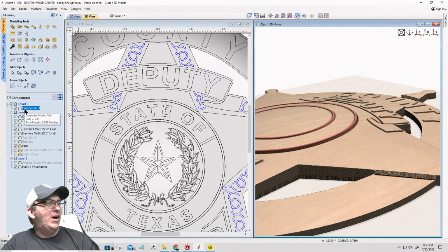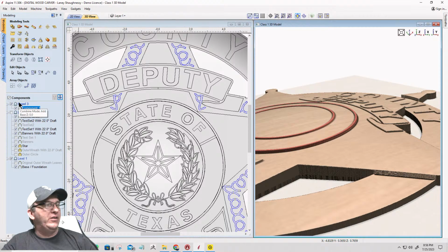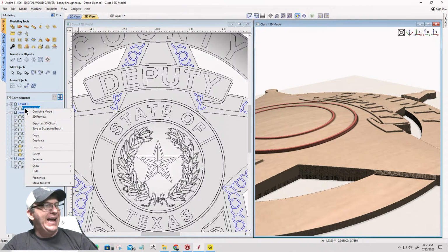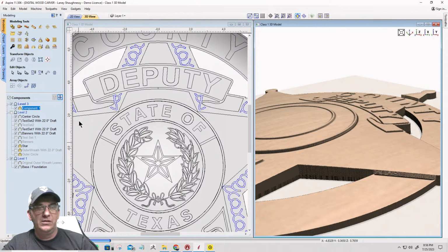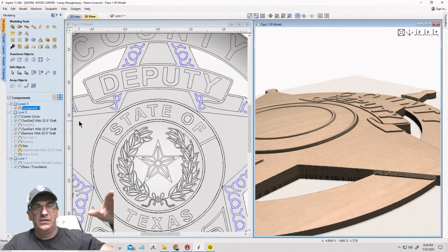Now, watch this. Remember when those two domes were merged 5 seconds ago, they were sunk down in that circle, right? You couldn't see them. Now that they're on another level and that level is adding to level 2 below, I can now change this combine mode to merge, and they will stay put sitting on top.